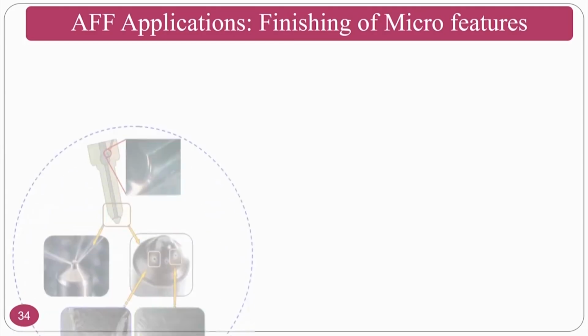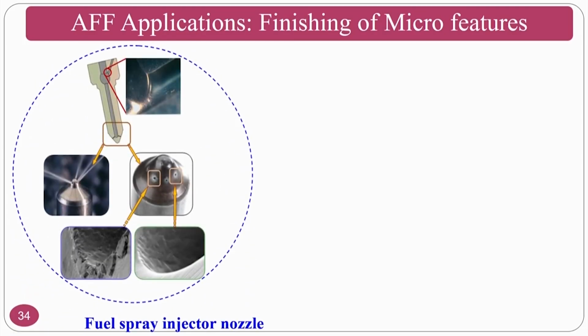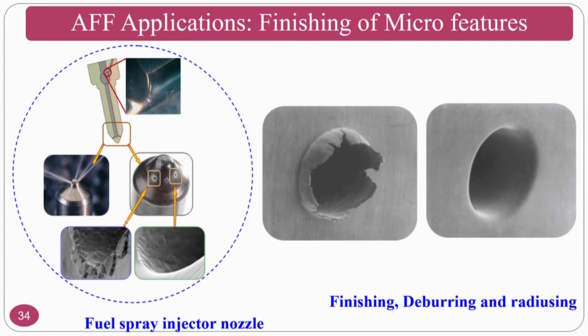Normally you can do it for micro applications. The finishing of micro holes on fuel injector nozzles can be done, and the recast layer can be removed and finished. At the same time, there is deburring. I was talking about deburring in some of the cases. I kept this particular slide exclusively for those people who couldn't understand what a deburring operation is.